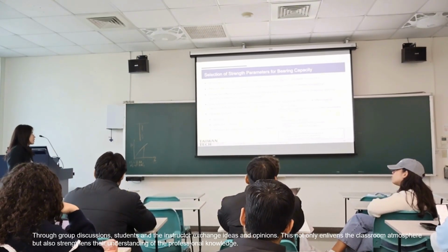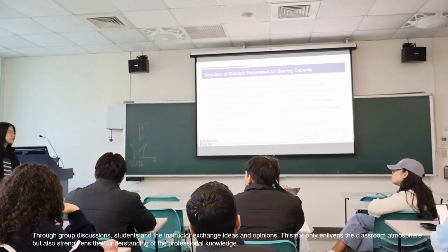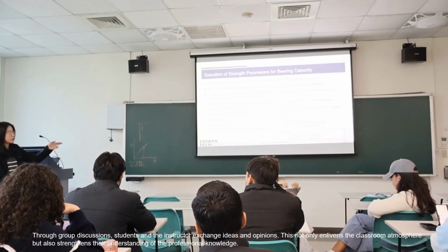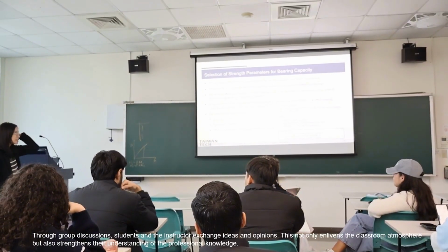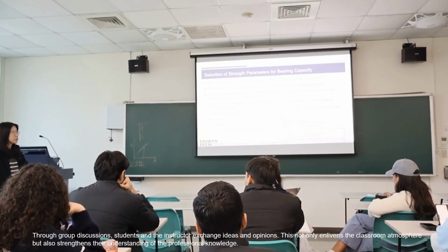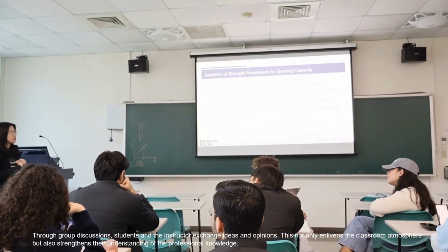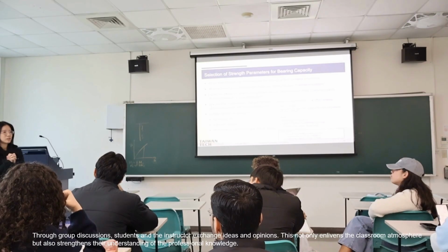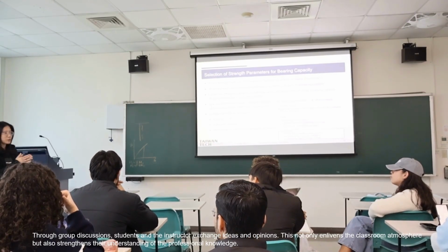But again, I want to say that if it's clay soil and we consider the long term, for clay soil we still have c prime, so we still can get bearing capacity for the long term. But once you finish your homework, you will see why for clay soils we have to consider short-term conditions. That's it for the whole idea of shallow foundations.